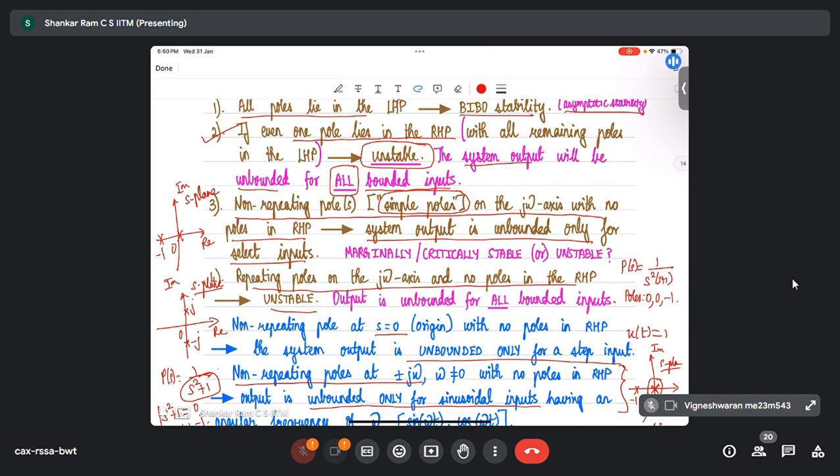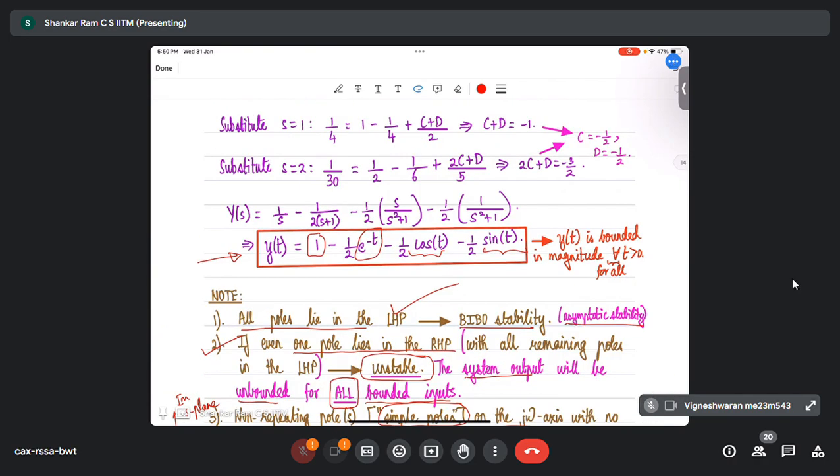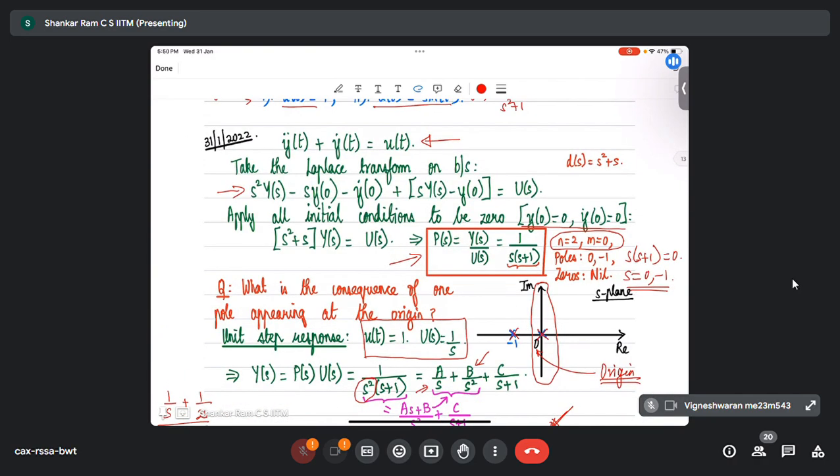See, for example, second order systems are going to come in suspensions. First order systems are going to be characterizing brake system models, powertrain models, and so on. Second order systems once again will characterize lateral dynamics. When we deal with cornering, we are going to see all those things. In fact, if you scroll down the video, if you have some time and you're curious, go downstream, you will see all these equations coming. But the equations are going to become a little bit more complex. It's not going to be as simple as what I'm writing here. We just start off with simple stuff so that you and I can become comfortable.